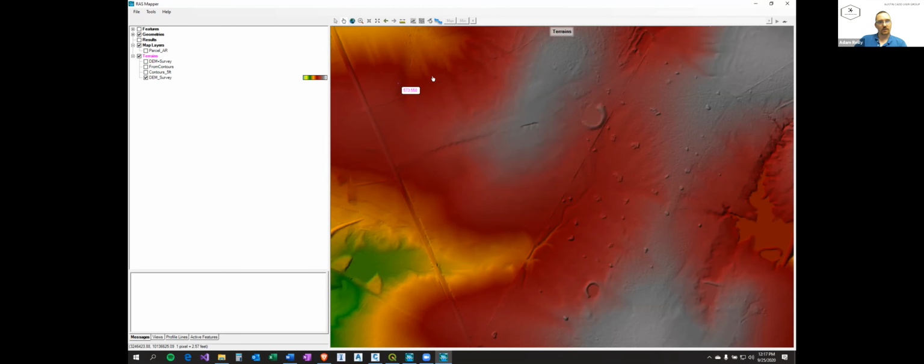Yes. All this DEM data that I brought in is what TNRIS had set on their metric UTM, and my survey was on North Central Texas. It did the conversion automatically for me because I had that set. On the back end, it's built on top of GDAL, the Geospatial Data Abstraction Library, so it's making the translations off of GDAL and is intelligent enough to pick it up.